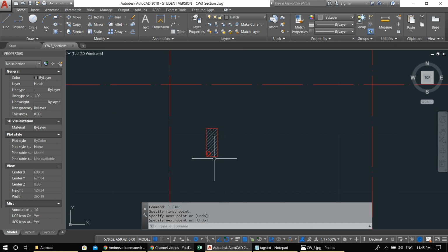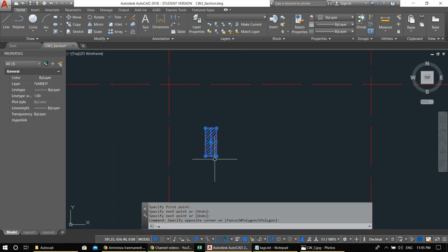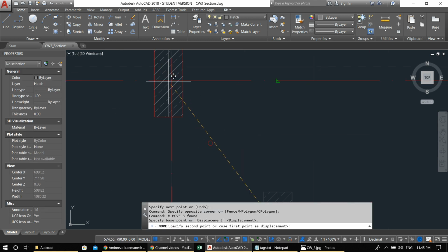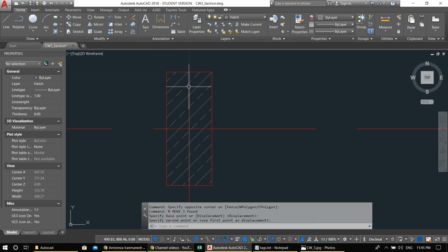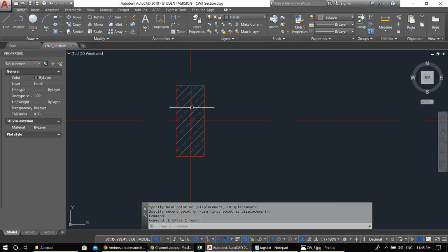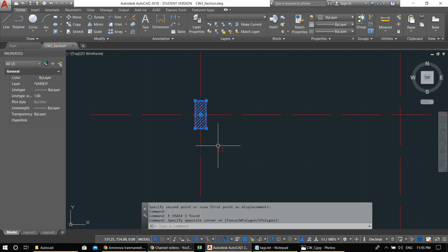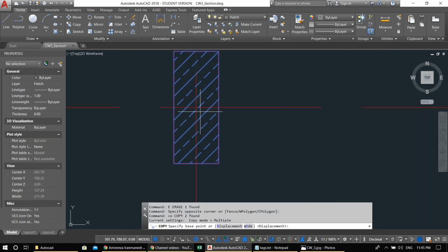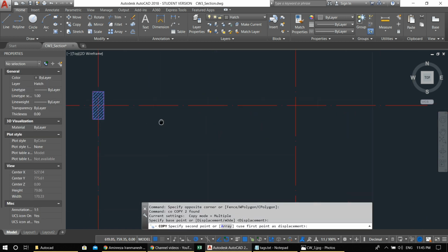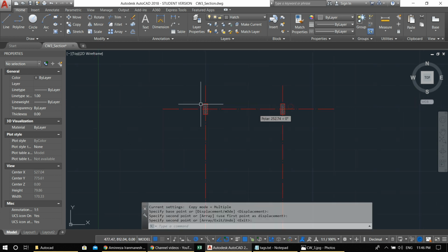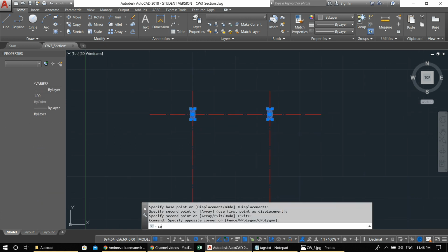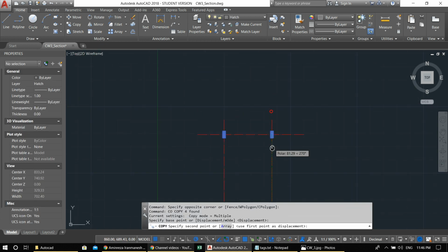I'm drawing one line in the middle because I want to make absolutely sure that I'm doing this correctly. I had drawings where the AutoCAD suggestion guideline misled me by a few millimeters on a grid drawing, which will mess up the entire drawing. So I'm moving this here, then I'm copying the entire thing down.